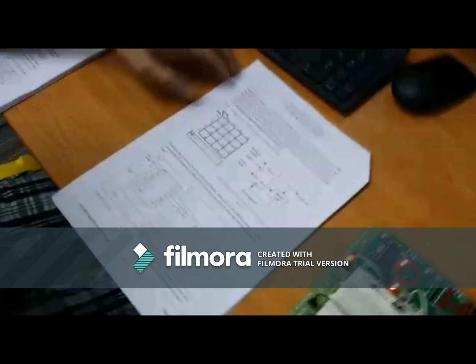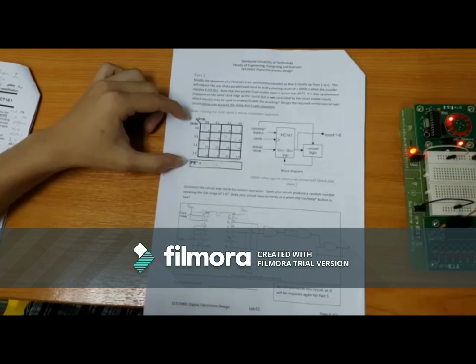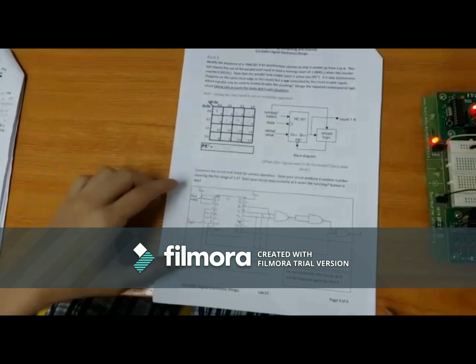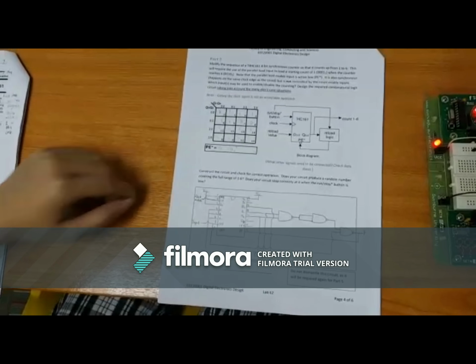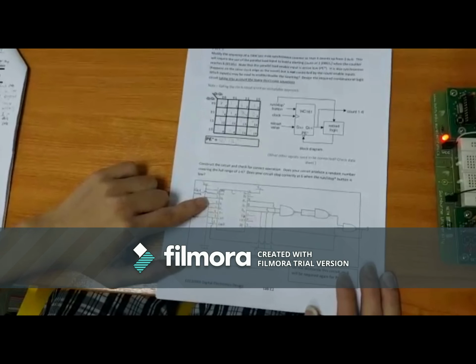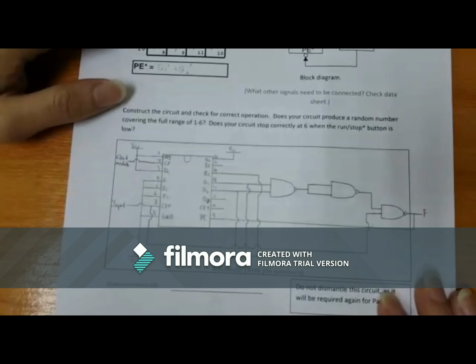This is our lab data, and this is the truth table of part 3, and this one is our diagram. As you can see from the diagram, D0 is connected to VCC so that the count always starts from 1.